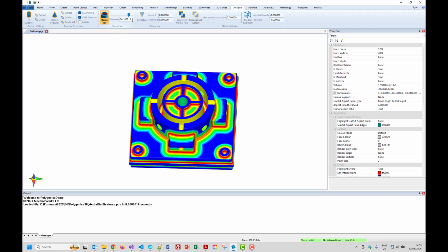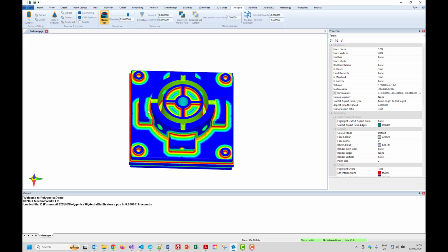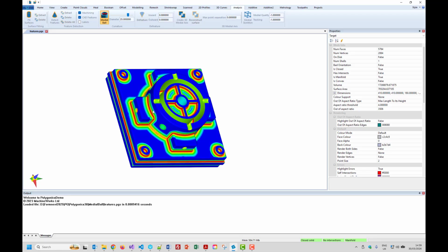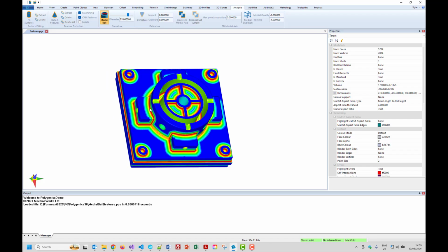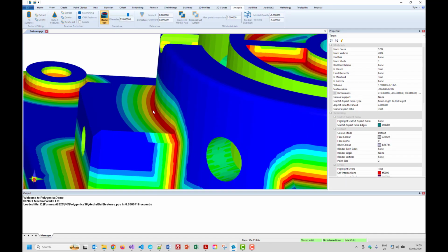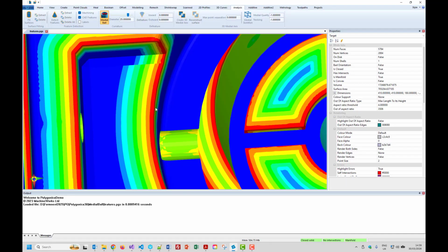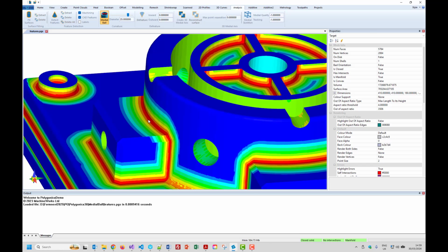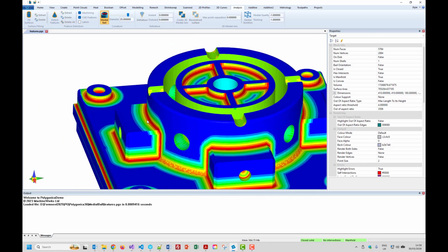So okay, let's pick something like 25, and at 25 you can see these areas are dark blue, but for example you can't machine the top of that, or you can't put spheres onto the top of that, because this other wall is getting in the way, and there's no fillet there. It's just a sharp edge, but you basically can't get a large sphere into that point.